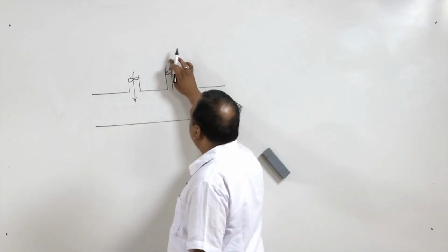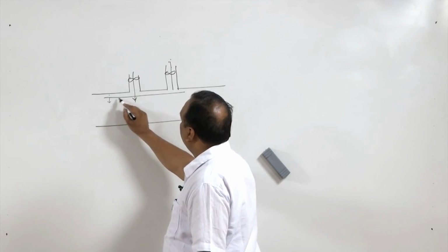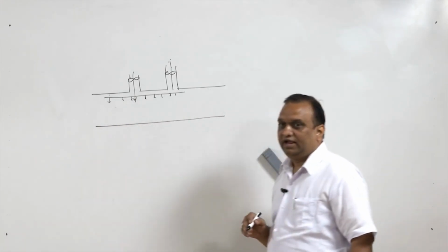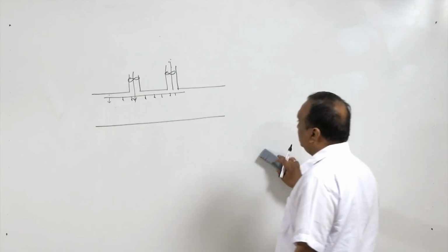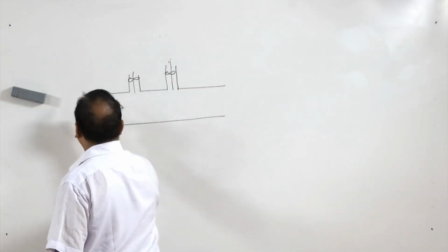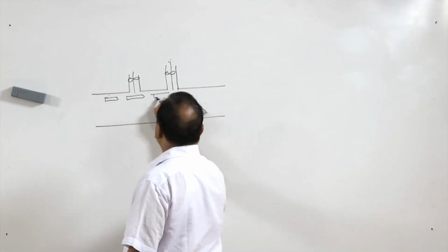Sometimes through the supply shaft a ducting is also done up to a certain extent so that the air is uniformly spread. If the tunnel is not very long, jet fans are used. Jet fans are the fans which throw a jet of air with very high velocity.